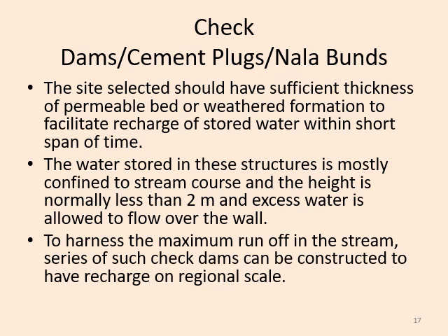To harness the maximum runoff in the stream, a series of such check dams can be constructed to have recharge on a regional scale. So it means here that not only one check dam or one nala bund, a series of nala bunds can be constructed across the stream or nala or khad to harness the maximum runoff and to recharge on a regional scale, meaning local areas.